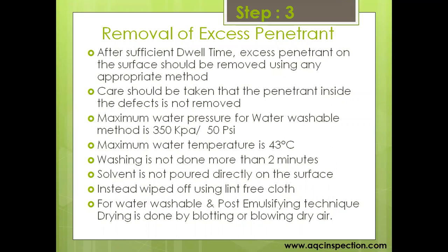In the solvent removal method, solvent is not poured directly on the surface. Instead, penetrant is wiped off with a lint-free cloth dipped in solvent. For water washable and post-emulsifying techniques, drying is done by blotting or blowing dry air, or sometimes using a heating furnace.